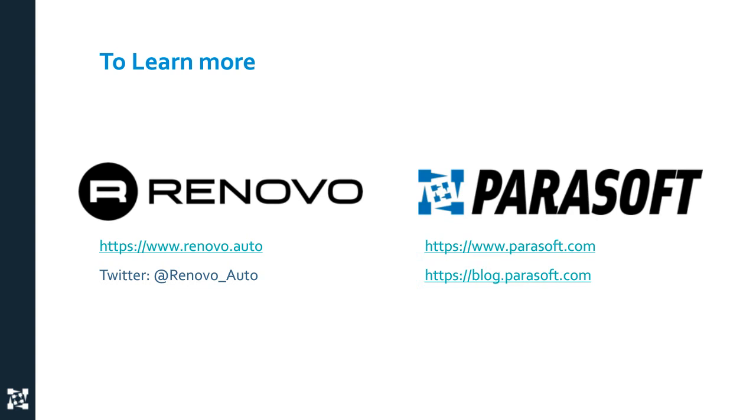One of the keys of being able to break that up into individual pieces is you can actually apply different workloads to it to obfuscate the identity of where it's coming from. Also, one of the benefits of doing it as a microservices system is you can insert workloads into the data flow at any stage, whether it's right at the output of the creation phase, where you're obscuring, let's say, license plates or faces before it gets stored in the local database, or you can store it in a local database in raw format, but before it gets transported off the vehicle, you're doing that obfuscation.